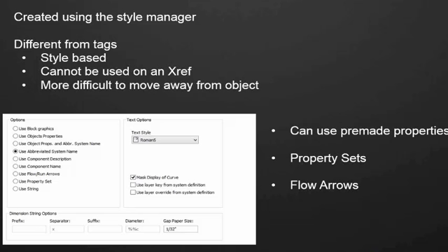So it tends to want to stay very close to the pipe. Labels don't reside on pipe fittings. They only reside on pipe objects, which is different from a tag. A tag can basically be associated with any type of MEP object. Labels have the ability to use some pre-made properties, such as the system name, the object property here, that would